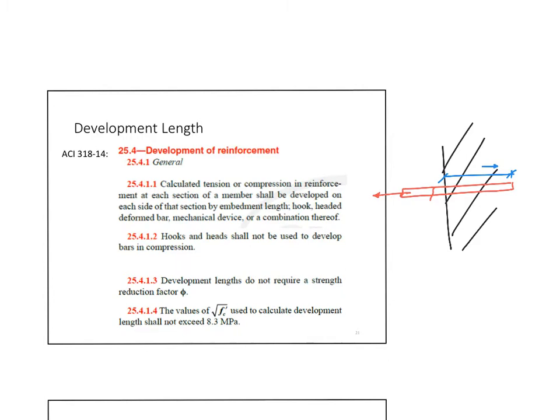Number two is to break the concrete. So you have something like this. That means you pulled out the concrete with you. So the bar was much stronger than the concrete, and the concrete will be pulled out. This is the second failure. Those two failures are good failures. Why? Because they are strength failures.